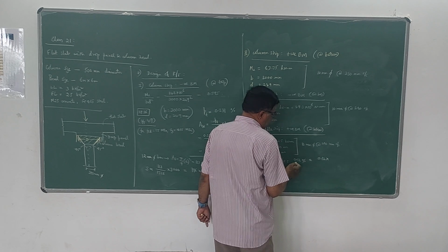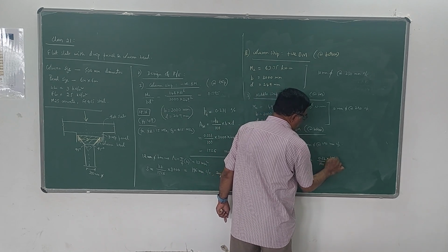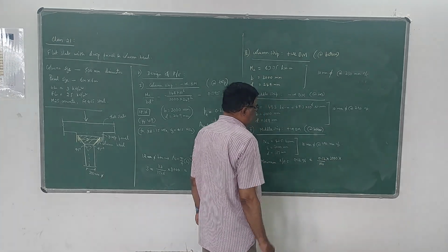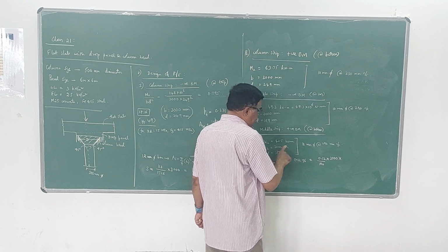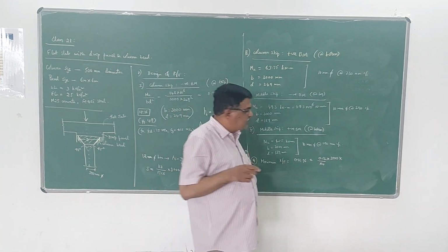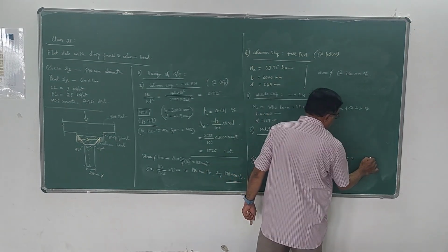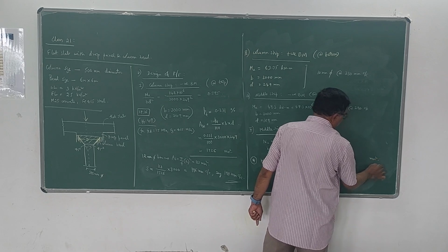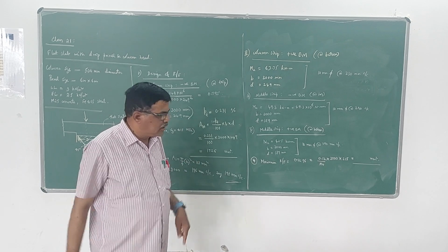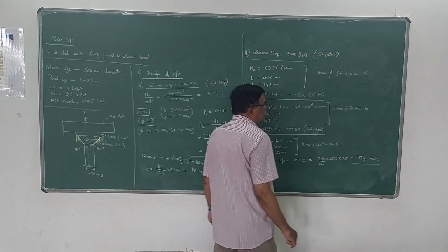Gross area we have to take. What is the total depth of the middle strip? For 189 we have to add 26 mm. Overall depth we have to take. So that is 215. So this is your minimum AST. What is the value of this? 774. Actually, this we have to provide.